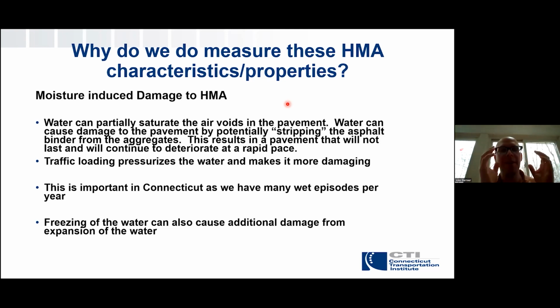And depending on your aggregate source and your binder source, you might have this interaction where water can actually peel it away, peel the asphalt away from the aggregate. So it takes both things, right? It's not necessarily one aggregate all the time, and it's not necessarily one binder all the time.